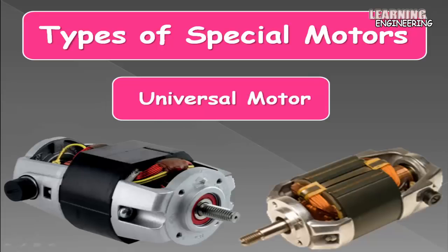Universal motor. The universal motor is so named because it is a type of electric motor that can operate on AC or DC power. It is a commutated series-wound motor where the stator's field coils are connected in series with the rotor windings through a commutator. It is often referred to as an AC series motor. The universal motor is very similar to a DC series motor in construction, but is modified slightly to allow the motor to operate properly on AC power.